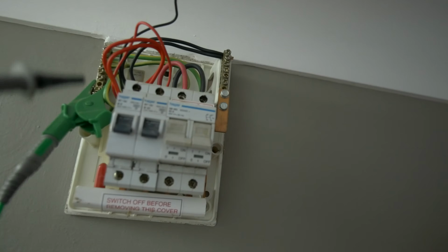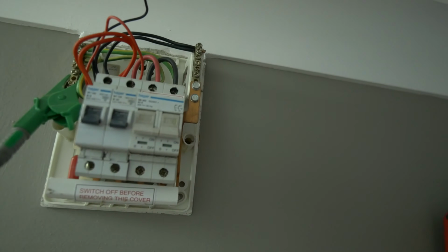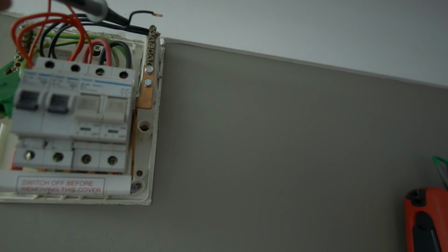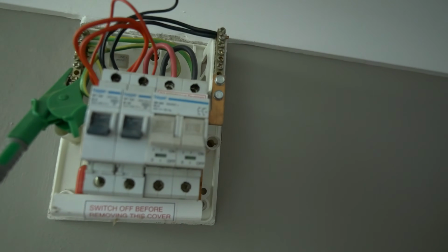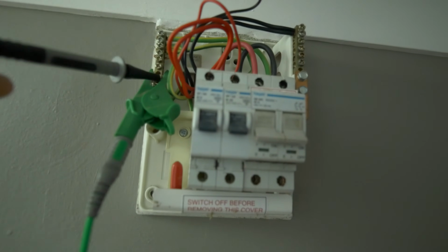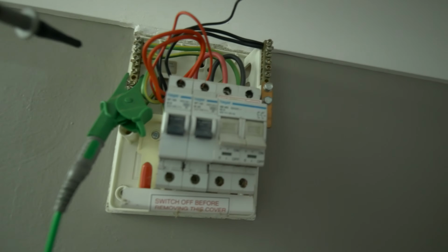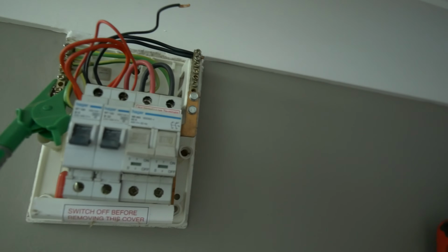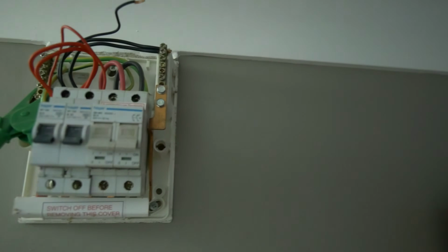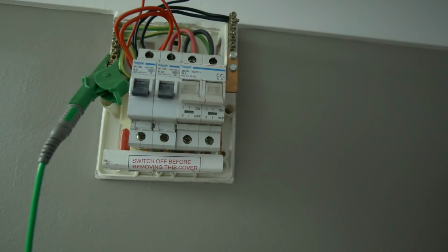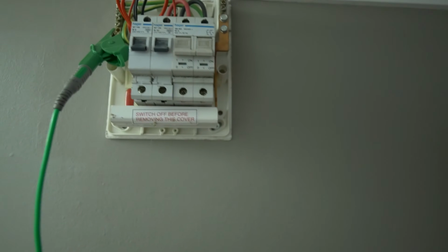Now that is because essentially the line would run through all of those lights and return back through the neutral. If you leave it connected in there with the socket line, the same principle happens and those two circuits end up connected together. So we want all of our earths in, all the CPCs are in together. Parallel paths, there is a single earthing conductor running back to the distribution board that supplies this, alongside the 10mm LSF that feeds down here. All of these circuits are in LSF, by the way, just to mention.